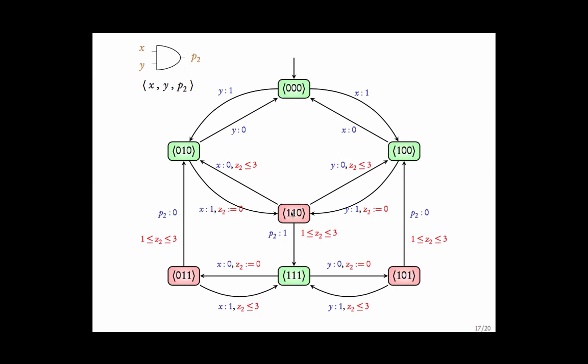It can become stable in multiple ways. Either the value of the inputs can change or the output changes. For the output to change, there is a constraint. Okay, and you can assume that there are invariants on every unstable state. You can be unstable for at most 3 time units. So there is a bounded inertial delay.